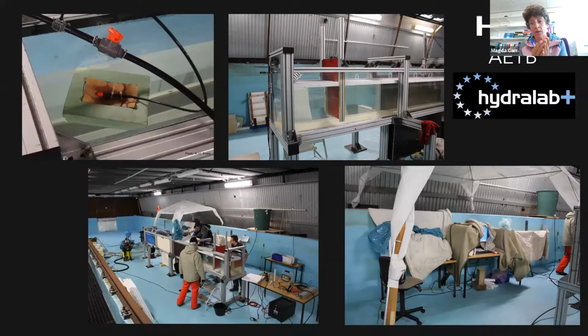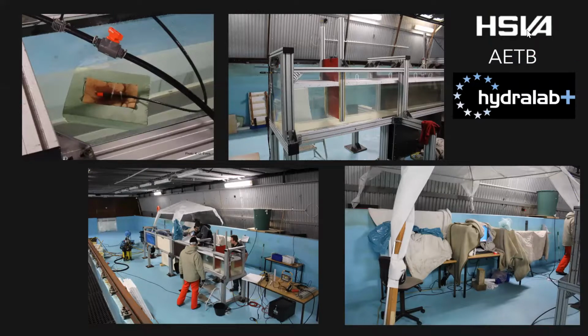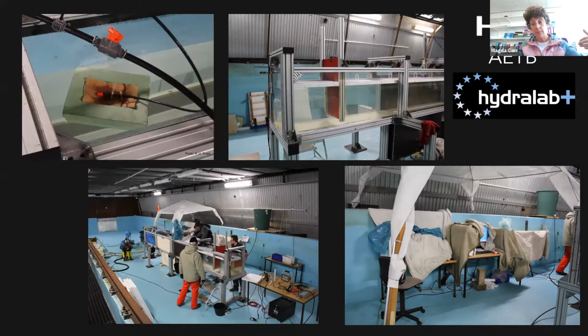There's a sorting distance of about 1 meter before all that mess comes off due to the generation process. But then when we're looking at the point where the wave interacts with the ice, that trailing mess has basically sorted itself out. And typically what we have is just a clean solitary wave. Then we get the second wave in the train, which is much, much smaller. So that's typically what we see in the experiments.